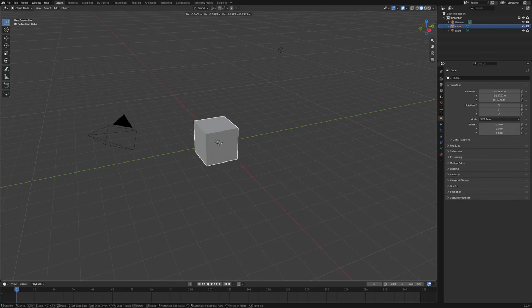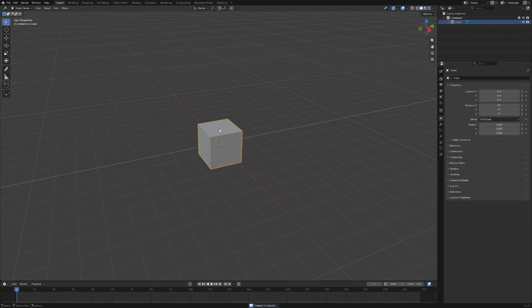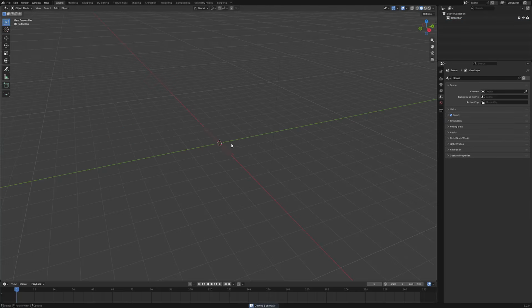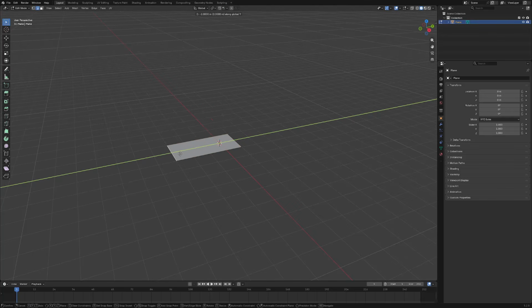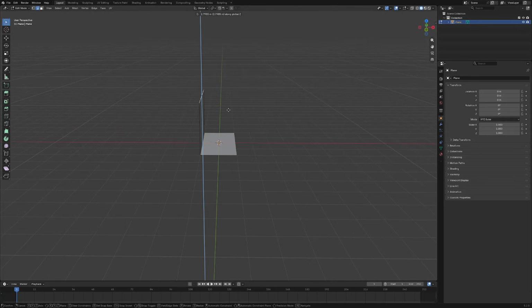You have your object that you're going to be working on, whatever the case may be. Let me get rid of these real quick, and you could use that, but I'm going to use a plane real quick. And I'm going to just start modeling a little bit of a modular kit, basically. So I'm just going to start working out onto the grid here. So pressing G Y, holding Control in edit mode, mind you. So Tab into edit mode. And I'm just going to start working out an idea of something like a scene that we want to create.